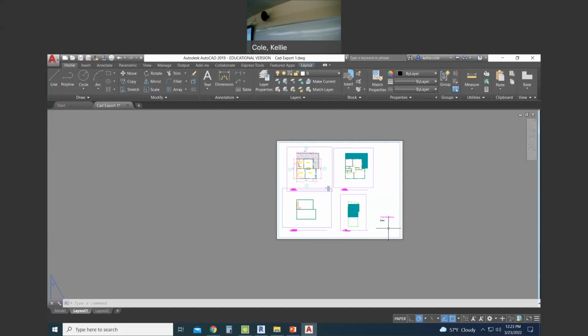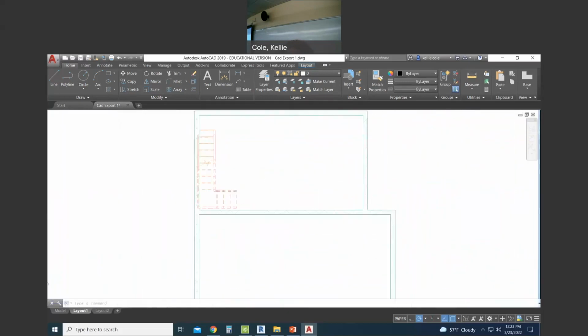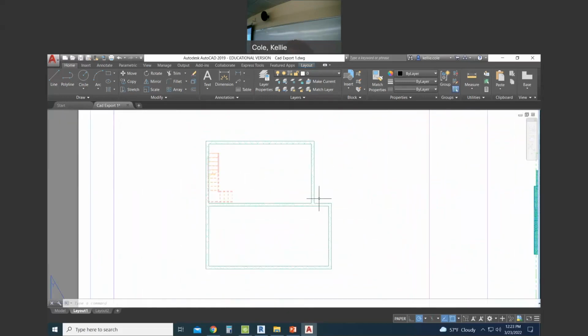And your little cheat sheet for your project house 1 says, for example, the red color means cutting. So if I want to cut out my floor plan, I'll zoom in. If I want to just cut out the whole perimeter, I might make the whole edge red. But if I just want to etch or score to show the CMU wall type in between, because I don't want a lot of pieces, I might use green.